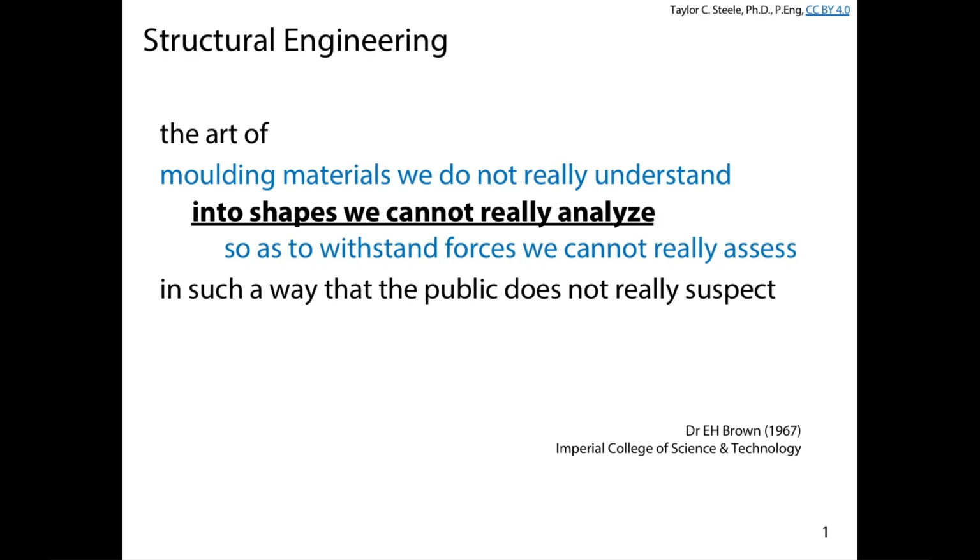And so we looked at some wide flange shapes, some WTs, some HSS sections, angles, flat bar, round bar, channel, for example. Those are the cross-sectional shapes that we have at our disposal to build with, generally speaking. Oftentimes we're not coming up with new structural shapes very often. Those shapes exist. There are several different kinds of them. They're tabulated in the handbook, so we know what kind of strength and cross-sectional properties we're working with, and we can just look in the handbook when we need to find that information.